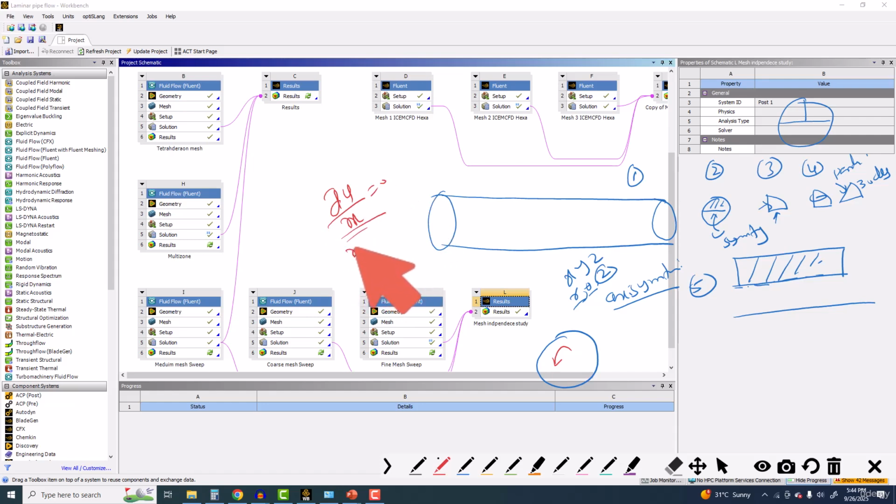Second, there is no change along the theta direction, meaning the flow is exactly the same at every location on the same radius; radially, at every theta, the same flow is there. This condition means we have axisymmetric flow. So we can solve this problem if I convert my Cartesian coordinates to cylindrical coordinates, and so I can solve this problem in two dimensions as well. Let's solve this proposition and see what differences we get.